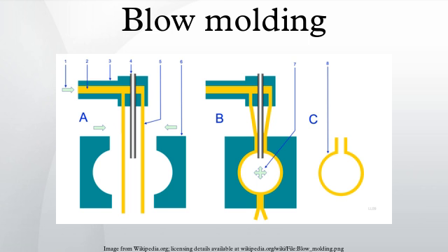In the single-stage process, both preform manufacture and bottle blowing are performed in the same machine. The older 4-station method of injection, reheat, stretch blow and ejection is more costly than the 3-station machine, which eliminates the reheat stage and uses latent heat in the preform, thus saving costs of energy to reheat and 25% reduction in tooling. The process explained: imagine the molecules are small round balls.